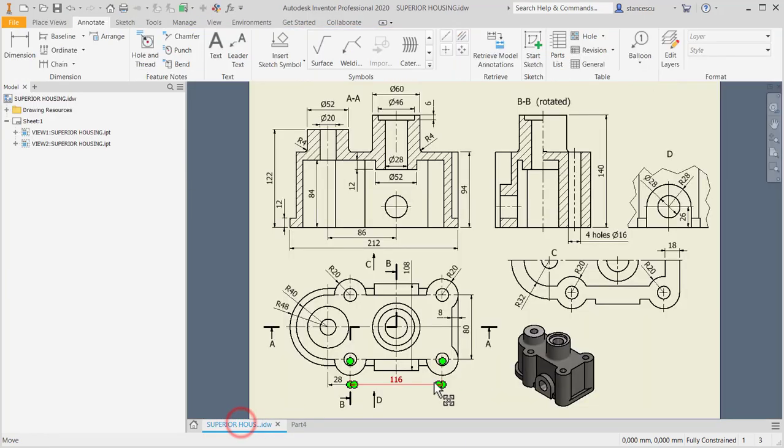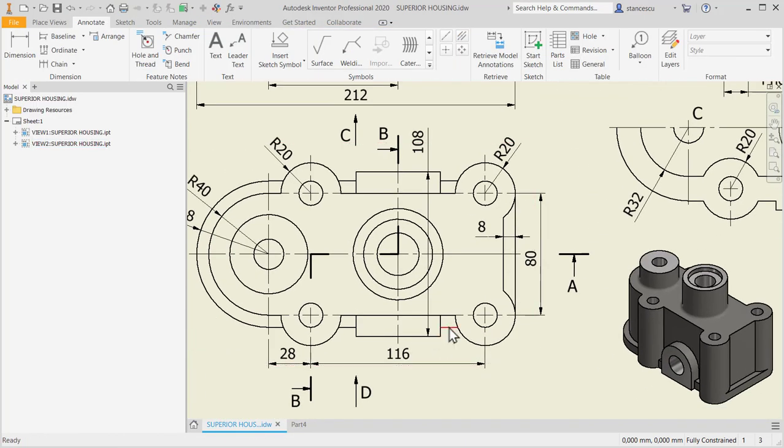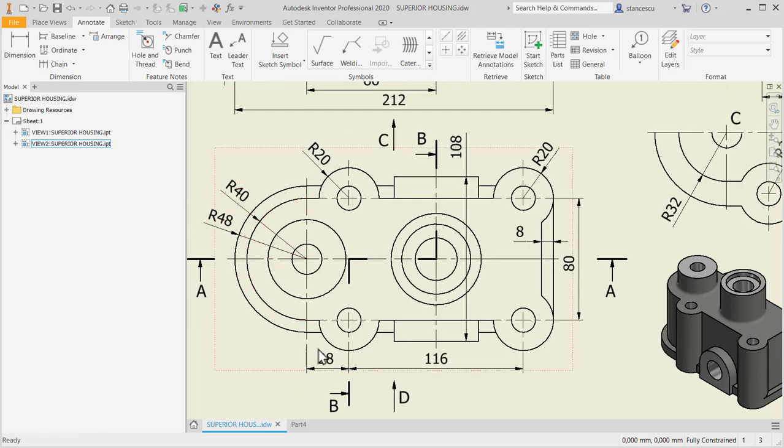There is another thing. As you can see, this is the platform, and it has a corner here which is not desirable. So I'll round this platform with a radius 8, because 8 is the difference between 48 and 40, to have a contour which ends with a radius here, to be not outside the cylinder.